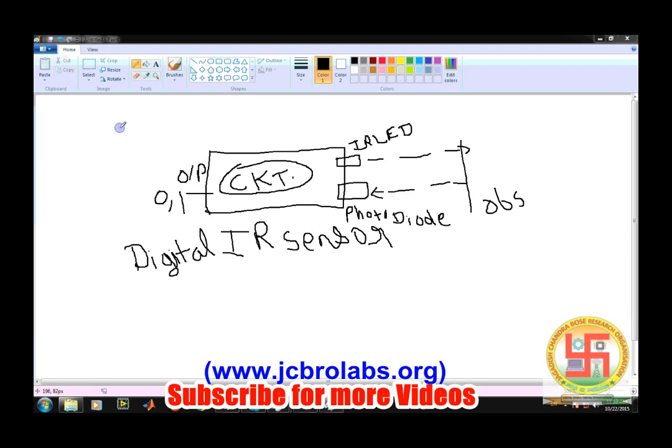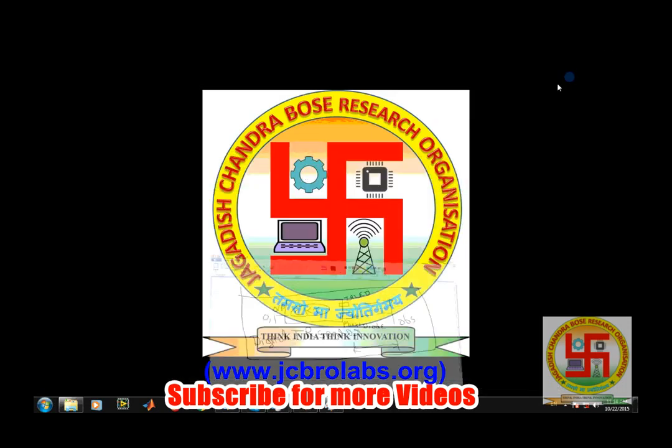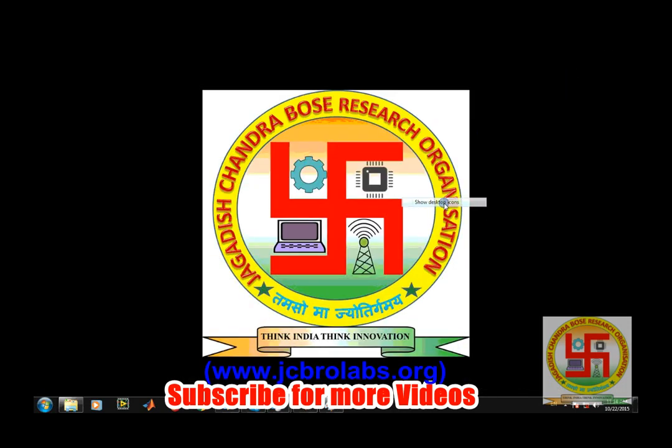Again, we discussed there are two variations, in the resistances and the reference voltage. Based on that reference voltage and the intensity of the LED, we can also change the distance of the IR sensor, that means after how much distance it will detect. So this is the basic circuit diagram of the IR sensor. If you have some doubt, you can also comment on the link provided below. We will now see a real IR sensor and how it works.